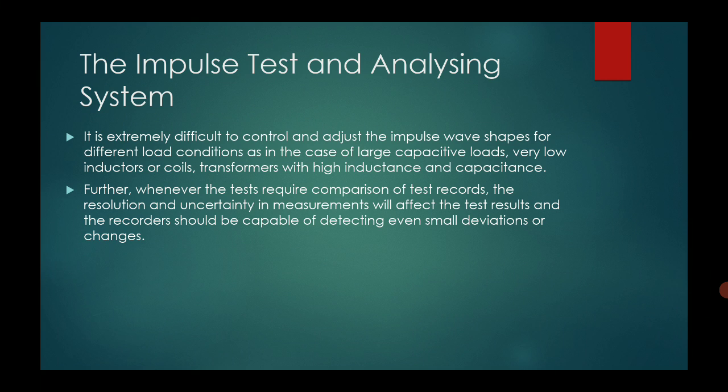And at the end, we'll talk about the analyzing systems of the impulse test. It is extremely difficult to control and adjust the impulse wave shapes for different load conditions, as in the case of large capacitive loads, very low inductance coils, and transformers with high inductance and capacitance.